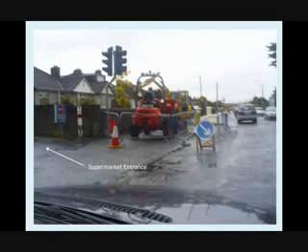Another photo here of some remedial works, urban works there. You can see the barriers used here have no reflective guidance on them. There's barriers next to traffic when it should be cones. There's a supermarket entrance here, traffic light junction. So just generally poor management of the traffic and the pedestrian management there, and not being up to the correct specification.